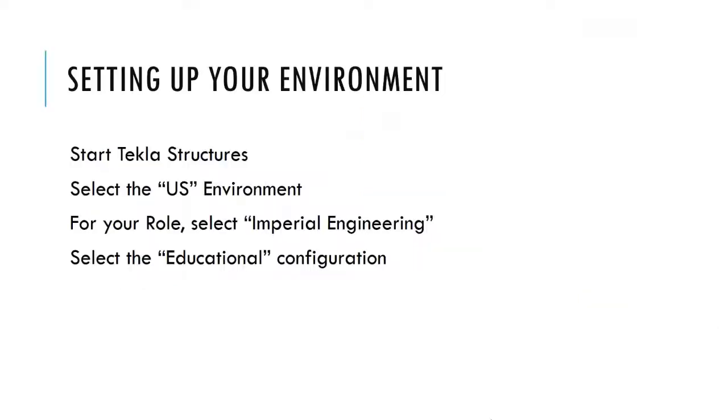Once you've successfully installed Qnect and Tekla, open up Tekla Structures on your computer. You'll need to select the US environment. For your role, select Imperial Engineering, and then select the educational configuration. If you run into issues, check out the quick guide from steelstuff.com, reach out to your instructor, or contact Tekla Structures. Your instructor can always reach out to me as well if there are any technical difficulties.